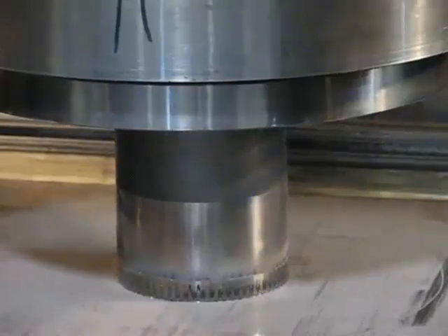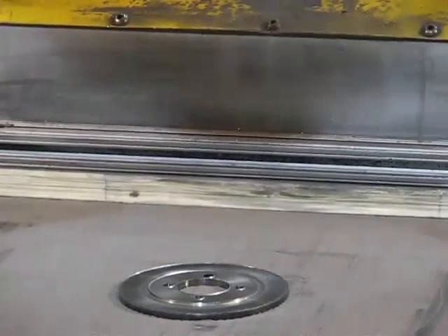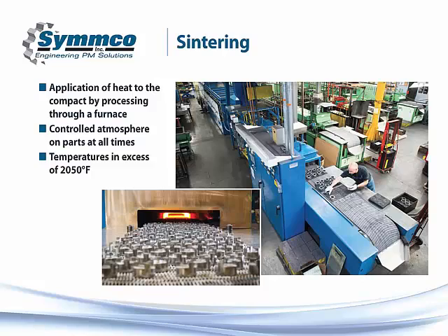And again, the video that we just saw, that very quick process, is what we call compaction. At this point, the particles are compacted. We've created that net shape, but it is what's commonly called green. It must be moved to a solidification process, and that solidification process is sintering.